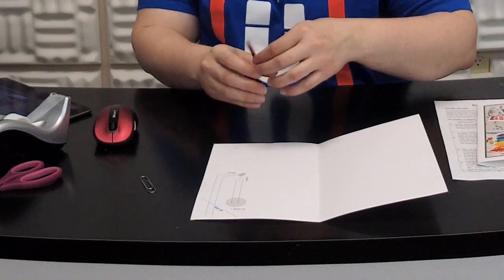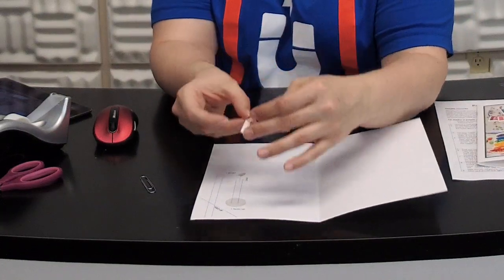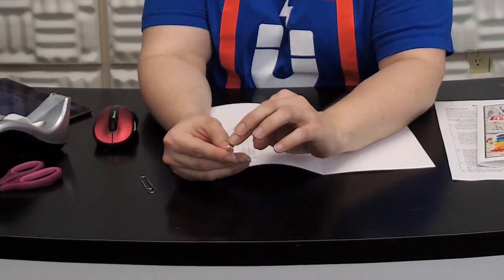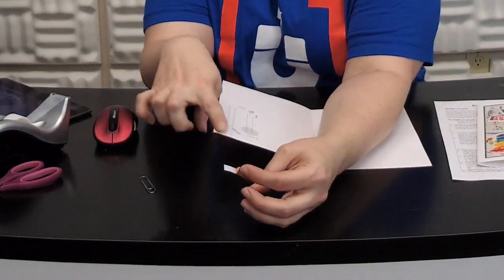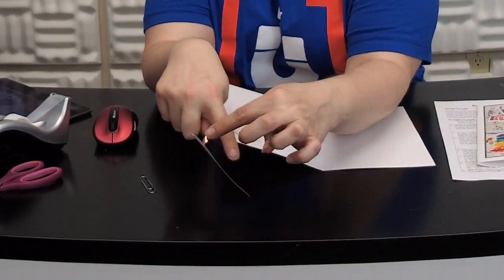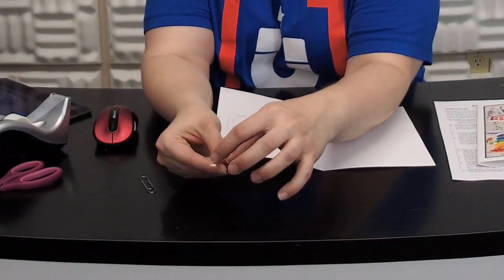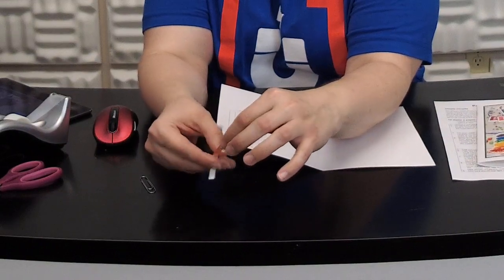Okay. So to do this, I've already pulled the backing away from my copper tape. And when you're doing this, I would not rip all the backing off the copper tape straight away, because this copper tape has a tendency to curl up on itself, and then it sticks to itself, makes a big mess, and becomes useless. So just leave the copper tape partly attached to the paper and peel as you go.